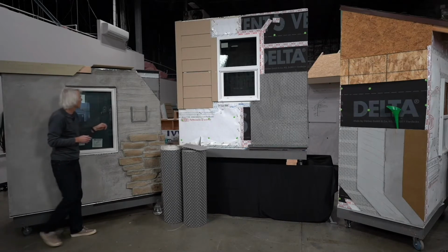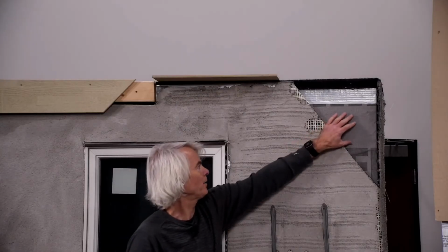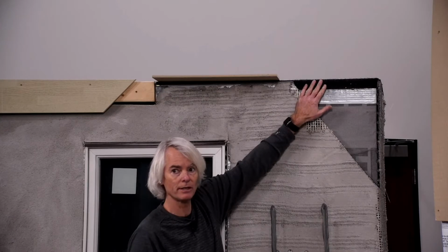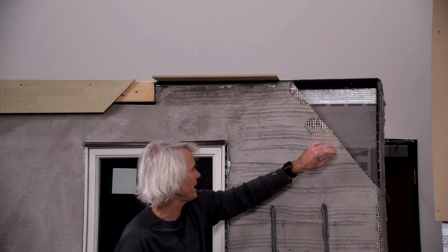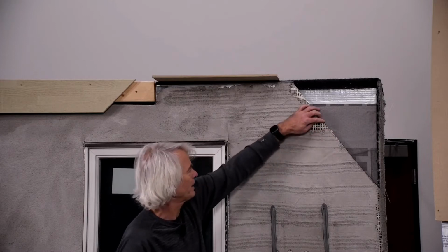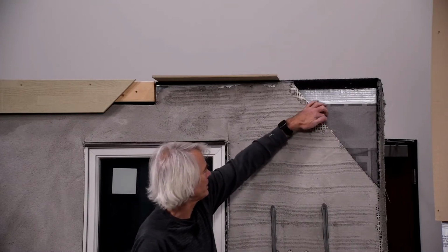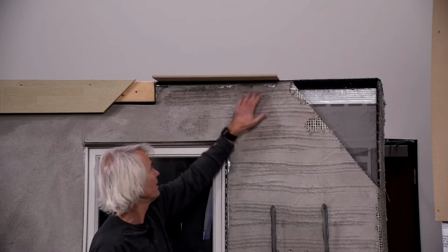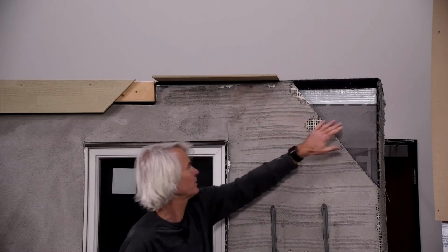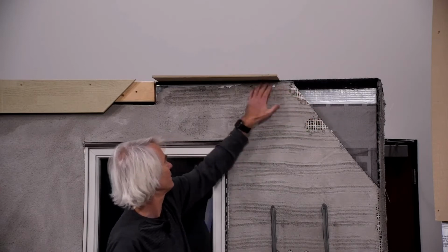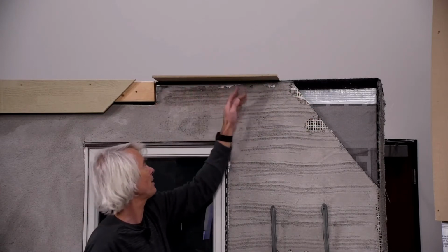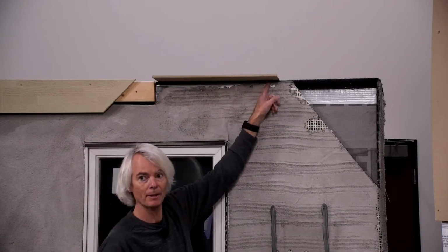The second one, let's really look at the whole layers of the wall, and here you can see this bug screen up here. This is a peel and stick weather barrier called Vent SA, and we've got the integrated stucco product with the lath on it right here. The casing bead sits here, so it goes weather barrier, then the bug screen. This piece then goes on with the casing bead on top, and here's our soffit with that same air gap right up here.